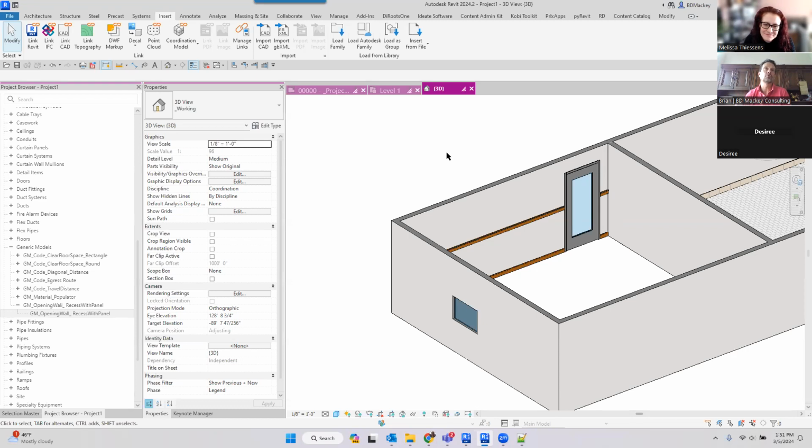And I think that's usually the bigger problem: somebody edits it, then they continue to work on everything else, and nobody even goes in and says, "Cool, I'm done. Let me go synchronize." So those are the things that I know when I go into clients' files and I tweak their groups or tweak their design options, I'm instantly hitting synchronize because I know I've taken ownership of everything. And some of my clients do giant design options, like an entire floor of a building can be a design option. I want to make sure I give that up for them. So yeah, it's a limitation. Just know what you need to do.